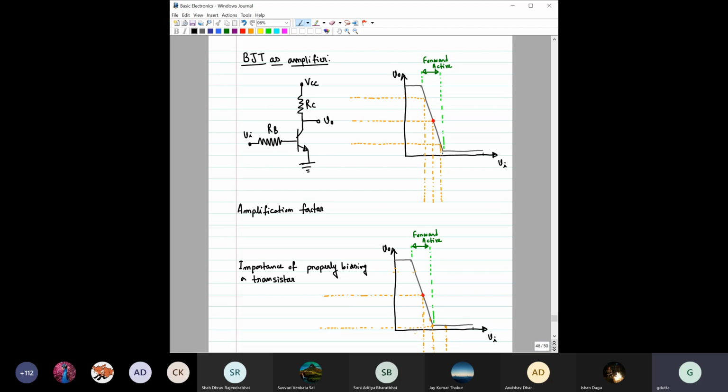When we talk in front of this microphone, this acoustic signal gets transformed into an electrical signal. The amplitude of that electrical signal would be very small, and we need to amplify it. Amplifying means the signal properties, like frequency, do not change. It replicates the same signal, but only the amplitude increases in the output. That is basically what an amplifier does, right?